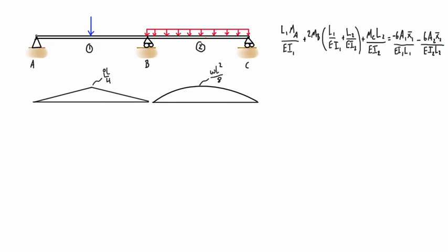But they might not always be 0. For example, if you have an overhanging beam, something like this, maybe with a point load at the end, M_A would no longer be 0. But M_A would be really easy to find, because you could just take a virtual cut there, take the magnitude of this point load times the distance, and you'd be able to find M_A. Typically the edge moments like M_A and M_C will be known or pretty easy to find just by using statics before you proceed with the rest of the problem.